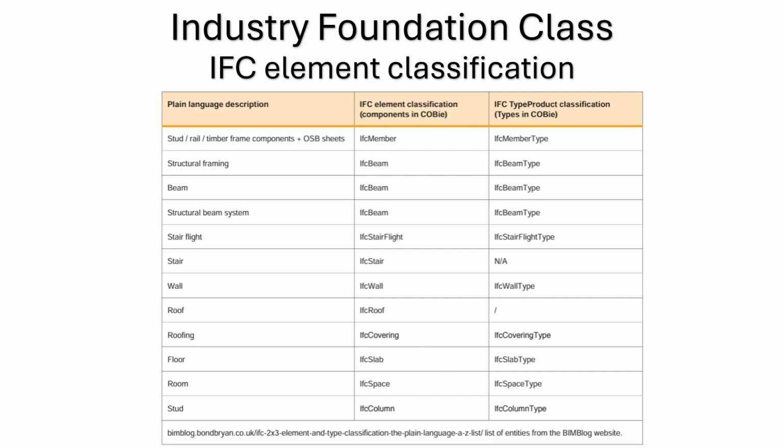All you've got is everything, if it's formatted correctly, all of the data in there, all ordered properly. So you've got a house with say 4 rooms or 5 rooms in that house. Each room you define as a space. And any object in that space, it could be a desk, a chair, whatever you draw that appears within that three-dimensional space will then be classified as in that space. When we call out a COBie file, all the data on that chair or the desk will be inside that space. Does that make sense?